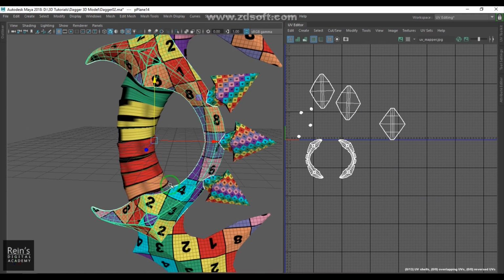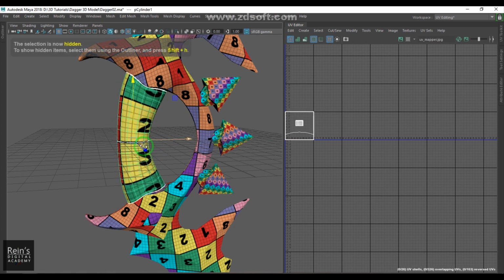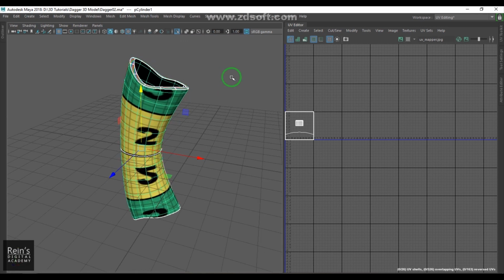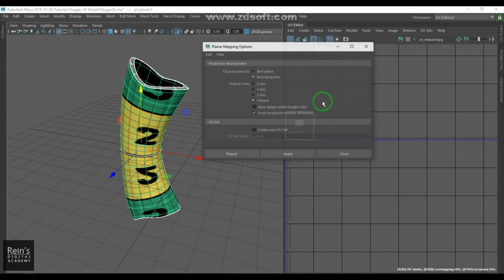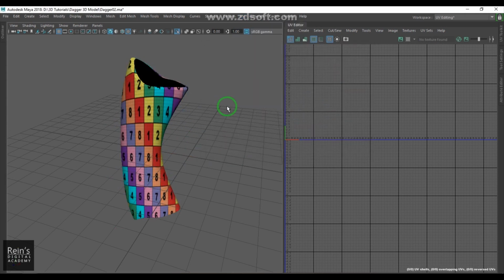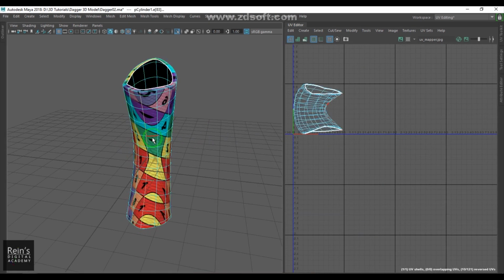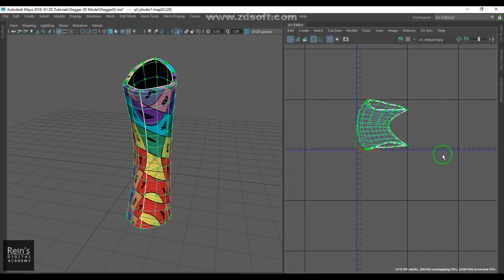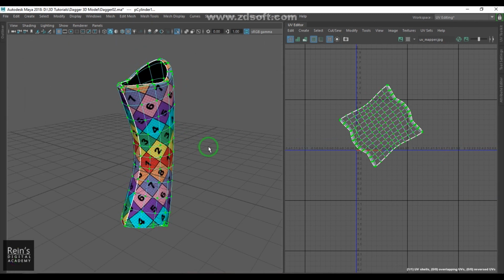So that's done. I select this model, hide it, and bring up this one. Okay, what I'm going to do is just apply a planar mapping. Don't worry about which mapping you are in and all, just select, just wanted to keep it like that, and then cut one line and then unfold. Press Ctrl U for that, and then you get the unfold. Very simple.